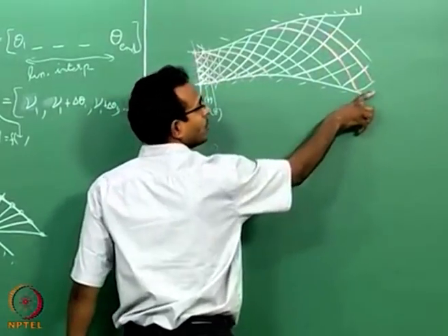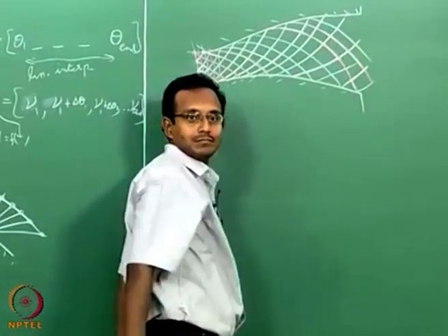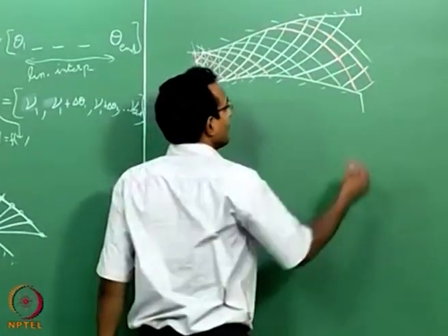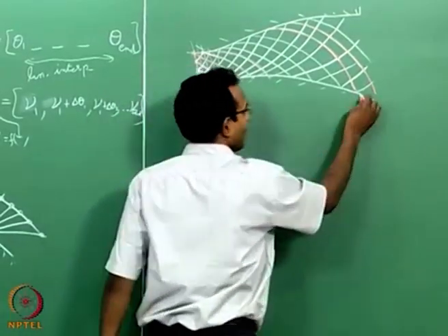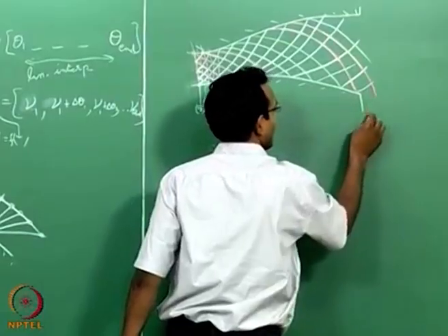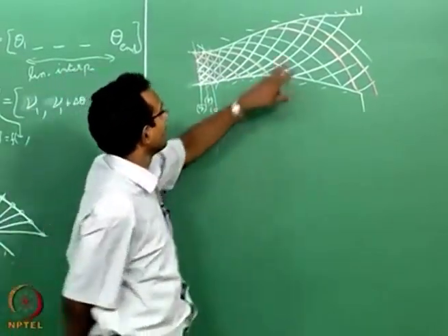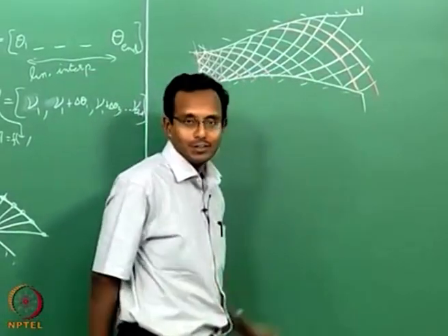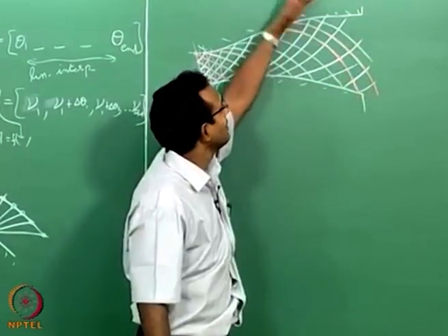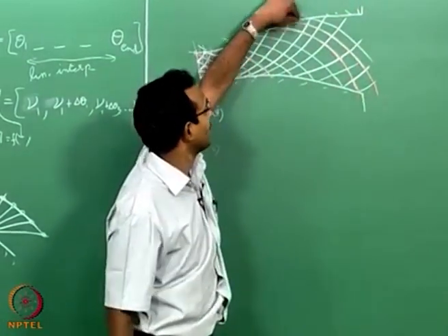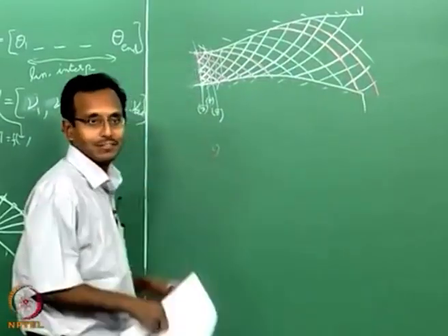Now I am going outside the nozzle on one end, while the other end I do not have any data. This is the problem with this. Now I need to be given the pressure boundary point, so I can solve for this outside region also. So I can solve up to here. I have gone past the nozzle on one side, while the other side I am still stuck somewhere here. I need data in this region. That is the problem with this kind of analysis.